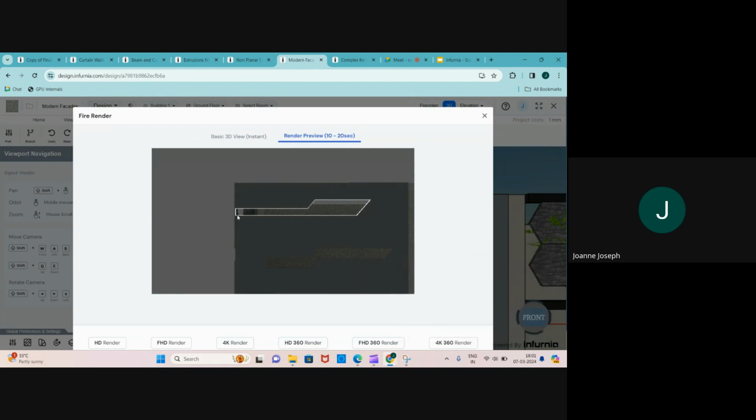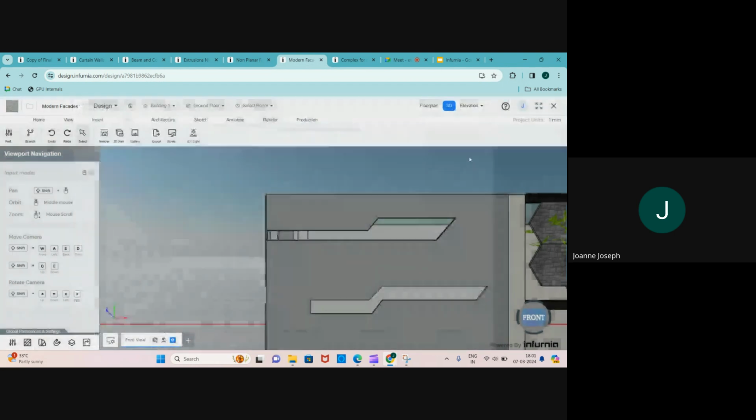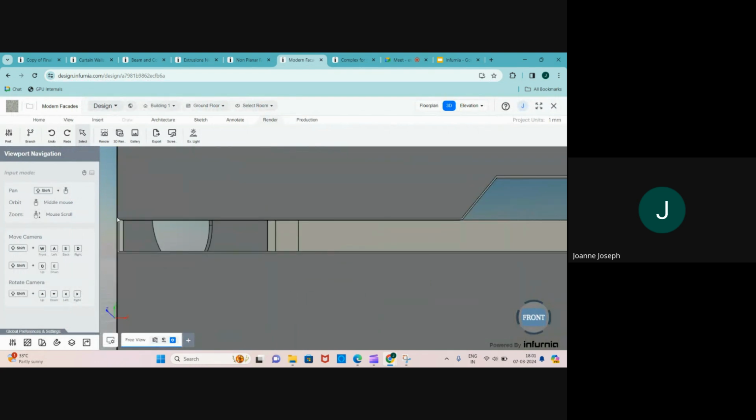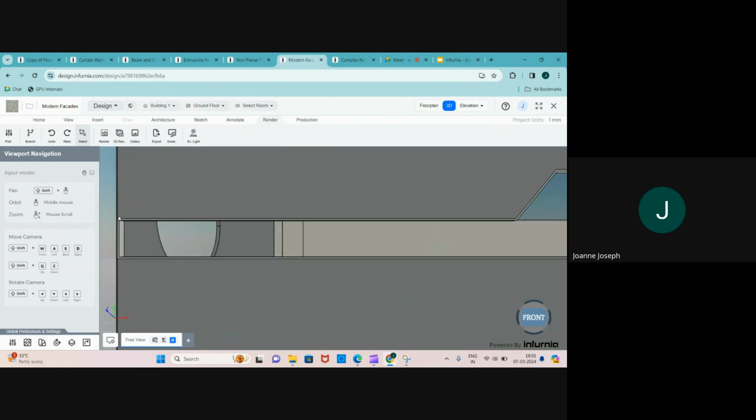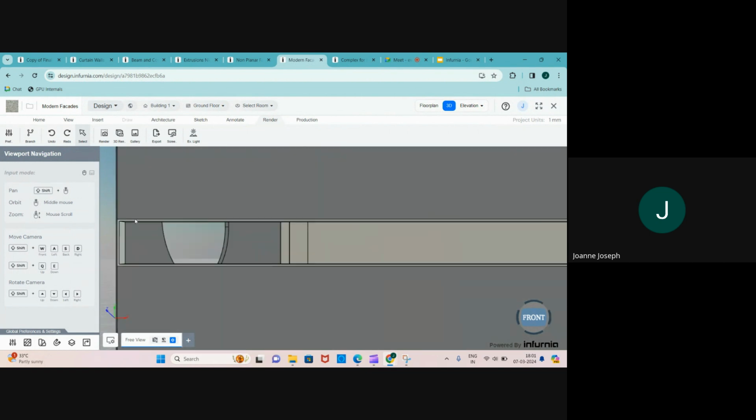Yes. So how do we create this kind of luminous strip happening around your cut? How do we create something like that? So what we do is we need to create another tiling cutting, another tiling extrusion, but this time it will be assigned a light property.